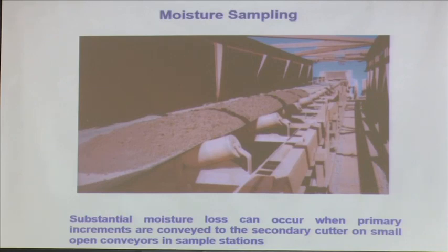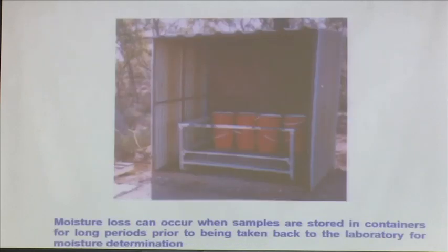So while I am doing it, how do I preserve them? That is very, very important. Okay. Otherwise my moisture analysis would go wrong. If I have collected it, I have to make sure that it is sealed at the point of collection. You must ensure that the moisture is not evaporating or getting contaminated with external moisture, and then you do the moisture analysis as quickly as possible, otherwise you may get wrong information. Okay.